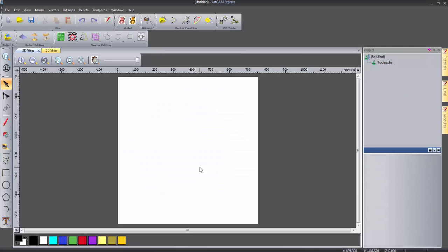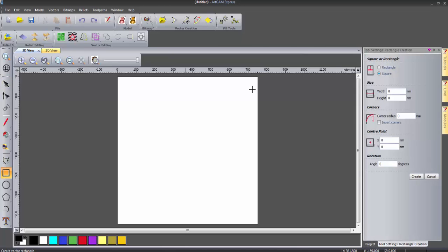The first thing I'm going to do is make the grid which makes up the chessboard. So I'm just going to create one square using the create rectangle tool. Make sure we're creating a square and use a width of 50mm and a height of 50, as this is in convention with chessboards. So I'm just going to create this and then center it in the model.